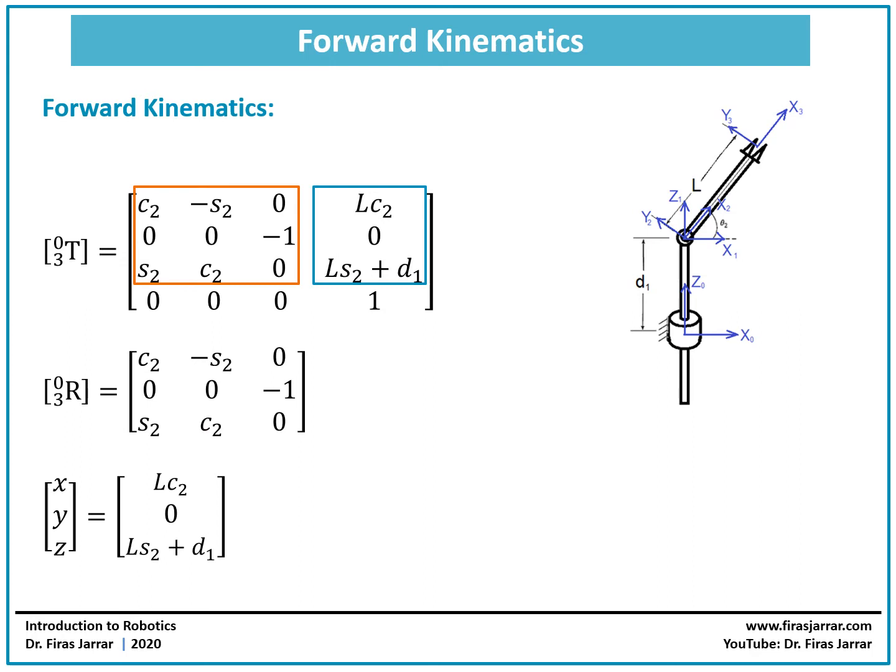So just as a reminder, the result of the forward kinematics simply gives us the orientation and position of the end effector frame with respect to the base frame. So you are simply answering the question, where is my hand, or where is the end effector of the robotic arm? For us human beings, this seems to be a silly question. Where is my hand?